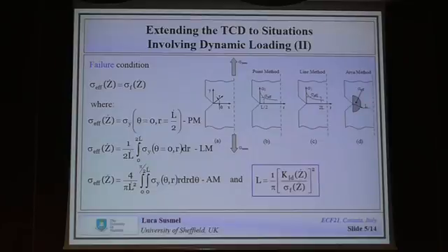But I really like the area method when I have to interpret what I'm doing, because in a finite fracture context, we can assume that this area, the one used to calculate the effective stress according to the area method, is that portion of material controlling the overall strength of my component. So we need to focus our attention on this area, because it's where the real party is when we are running our tests. So does this idea apply to concretes as well?